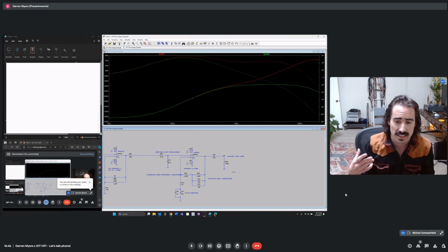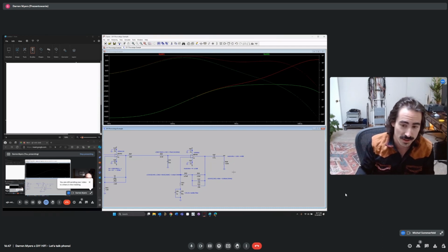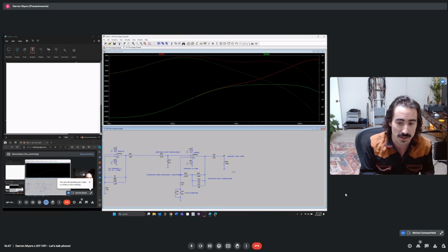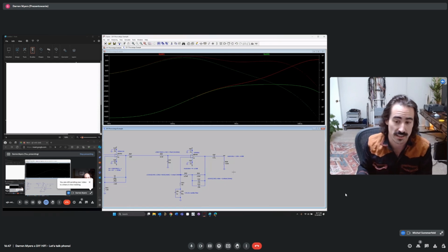And the fact that in a phono stage, because we have less gain at high frequency, that kind of works with some of the disadvantages of amplifiers, just having more open loop gain available at low frequency than at 20 kilohertz in most cases, and how that's advantageous.